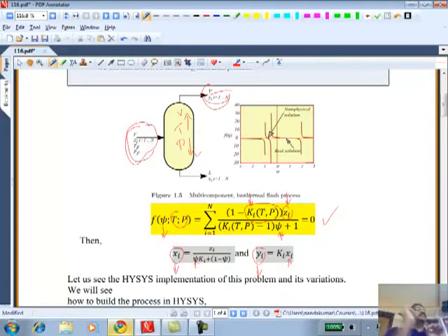So if I know the temperature and pressure such that it's mostly vapor, but it's at the boundary where if I reduce the temperature or increase the pressure slightly, it's going to condense into the liquid phase. So it's going to rain out. All the liquids, the heavier ones in the vapor, will drop off. So that will be called a dew point. The same thing in a bubble point.